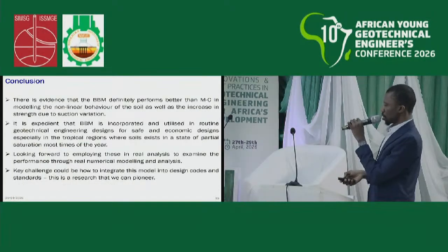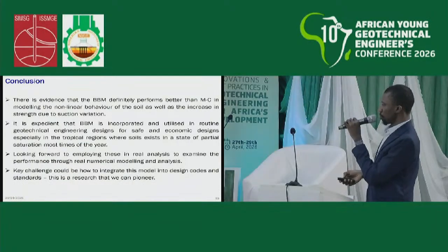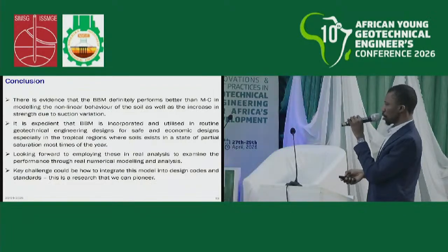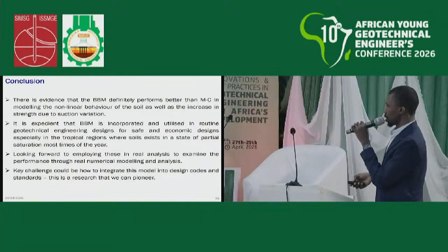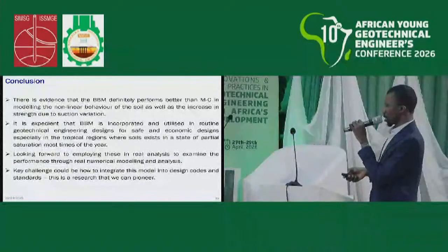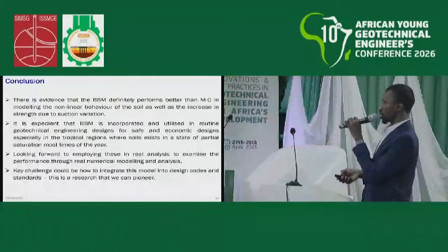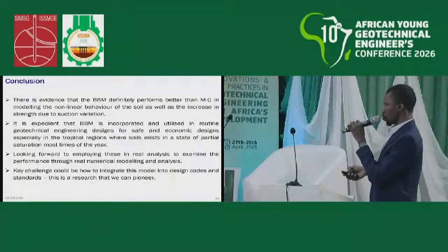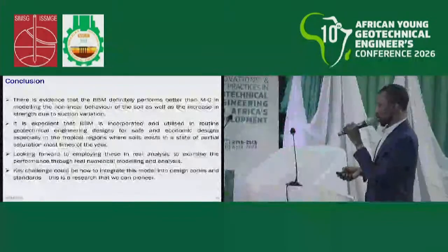And then finally, the conclusion: there is evidence that BBM definitely performs better than MC in modeling the nonlinear behavior of soil, as well as the increase in strength due to suction variation. It is expected that BBM is incorporated and utilized in routine geotechnical engineering designs for safe and economic designs, especially in the tropical regions where soils exist in a state of partial saturation most times of the year. I'm looking forward to applying this in real analysis to examine the performance through real numerical model analysis. And finally, the key challenge could be how to integrate this model into design codes and standards.